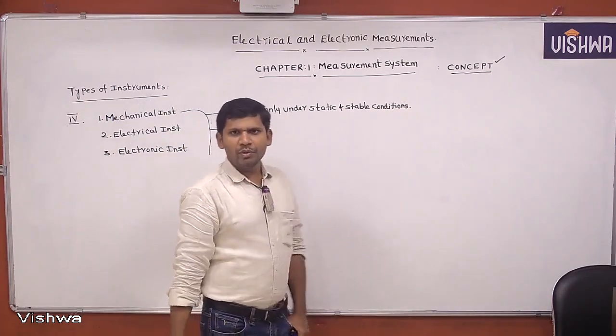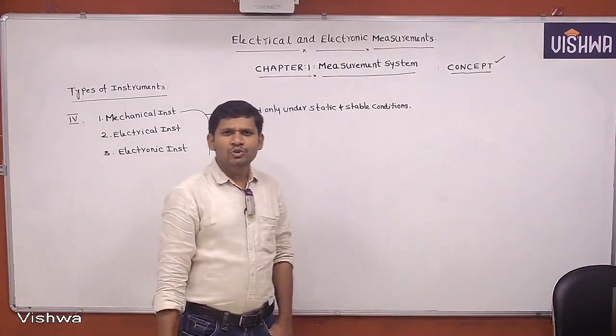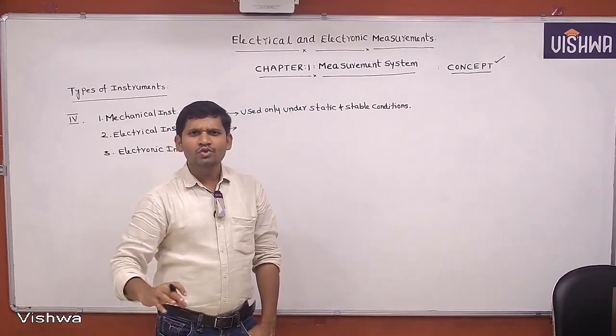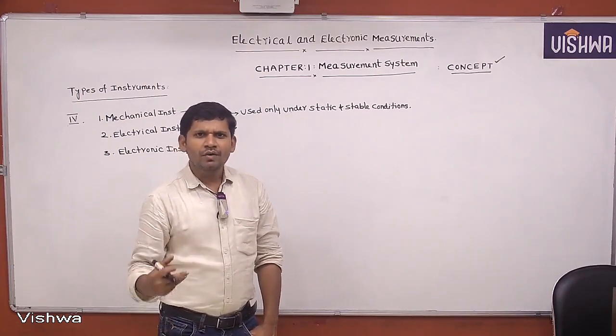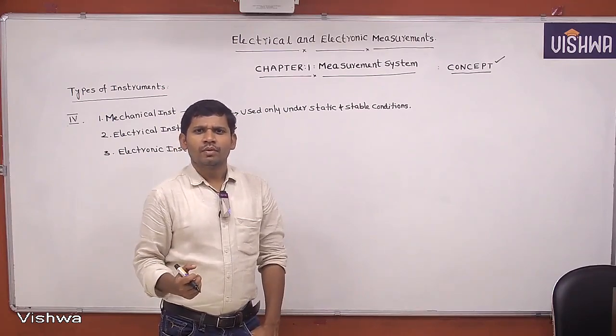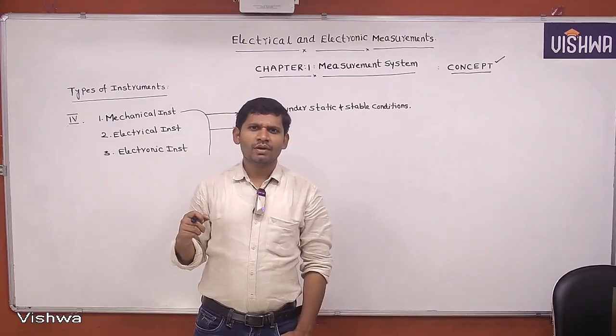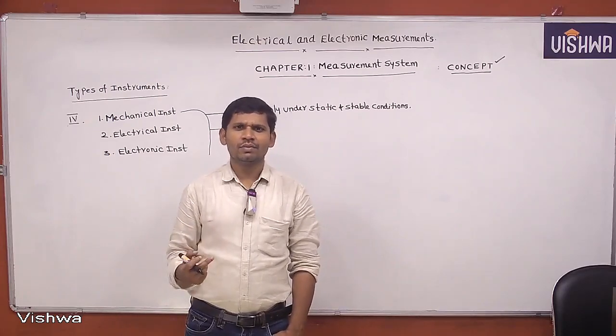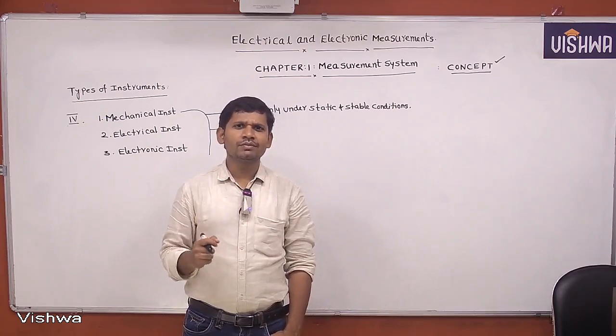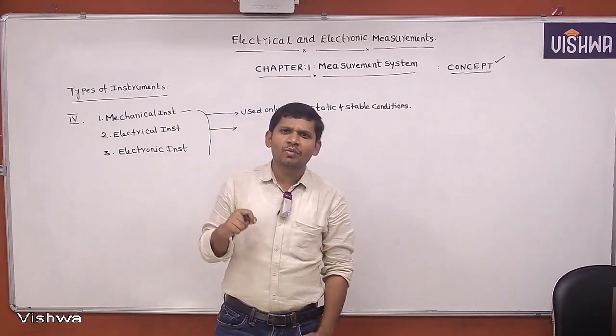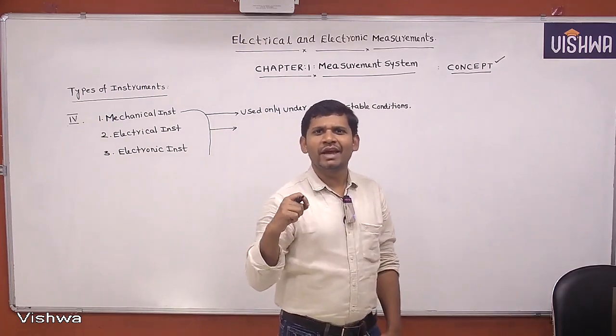One more point to remember: mechanical instruments have large mass. Because of the large mass, they offer large inertia, and because of large inertia, these instruments are not preferable under transient and dynamic conditions.